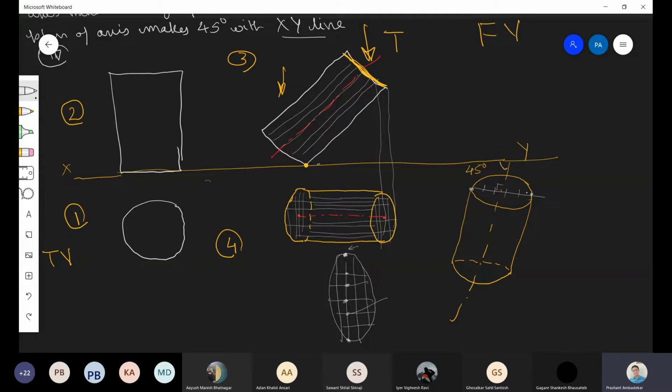And then from this point, which point am I talking about? Now this point. With this point, we will take another distance from here to here, and on this line cut arcs 1, 2, 3, and draw lines. So a mesh like this is created here, and then join the points so that you will get this ellipse, and then project the remaining things. This is already discussed in an earlier lecture, how to draw this view from this view. Just rotate it and draw.